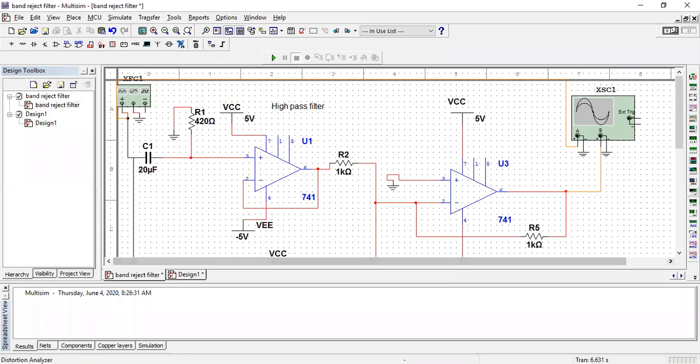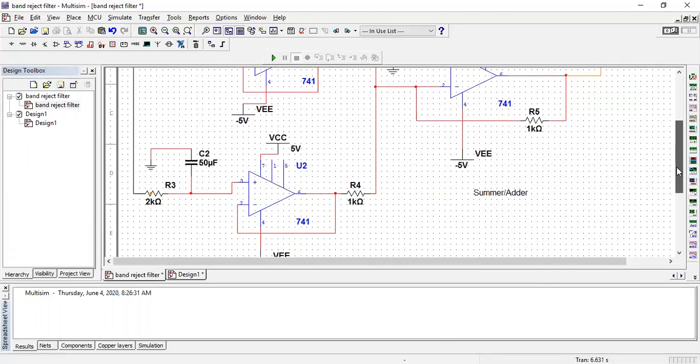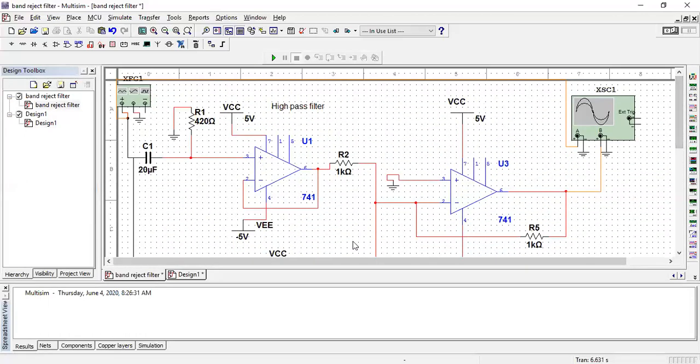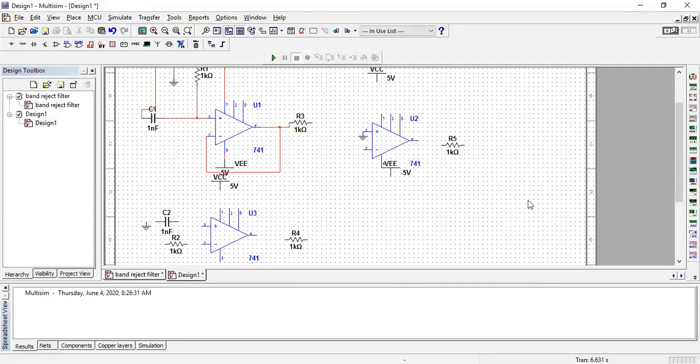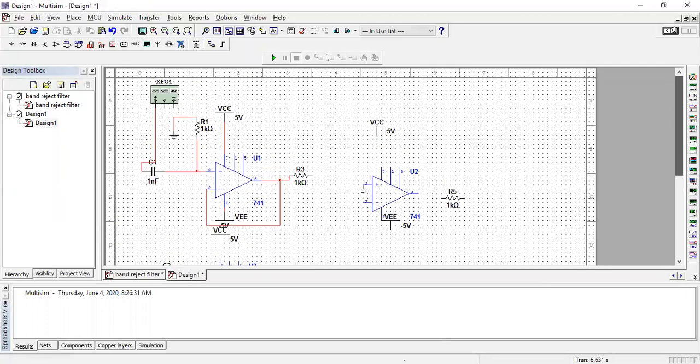So this is the example in which I have rigged up the circuit just as shown below. We have done this particular part, the other part we have not done. So you can do it in a similar way. I'll just show you how to place the CRO there. There are so many options here. From there you can see multimeter, function generator, wattmeter, oscilloscope. You need to connect here. You can just take it, select it, and put it on the screen.